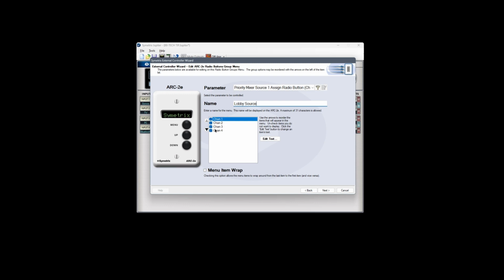This can be very confusing to keep track of, as in Priority Mixer 1 and odd-numbered priority mixers, Channel 1 would actually be Input Channel 1, or the Sonos. In Priority Mixer 2 and all other even-numbered, what is labeled Channel 2 here is actually Input Channel 1, or Sonos. The way to work around this is to simply swap Channels 1 and 2, and Channels 3 and 4, and so on for Jupiter 8 and 12.